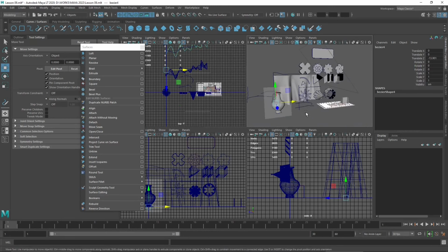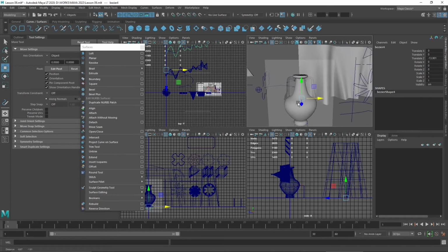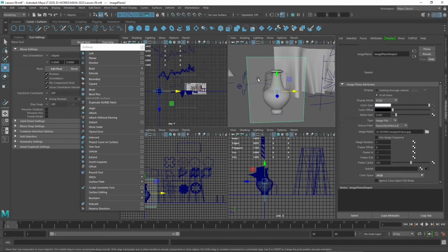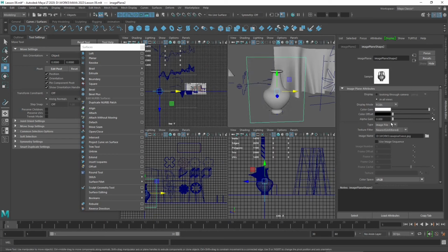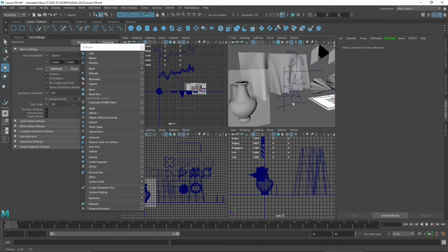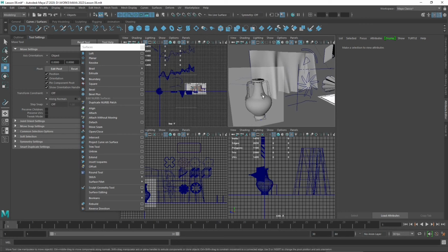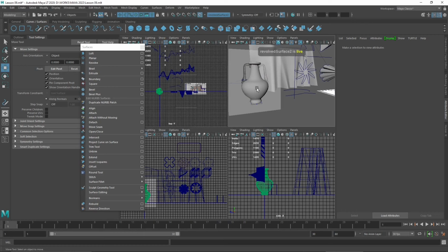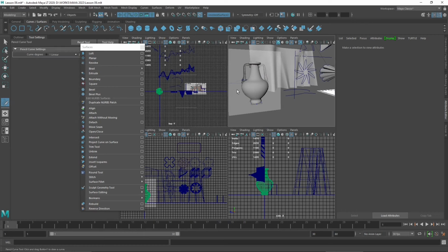For example, here we created a tent or a curtain using curves, and if we modify the initial curve, we can modify the result object. Same as the base here that we modeled before using a curve and tracing the image, and then we use the revolve tool. So we also saw how we can use images and references, which could be directly from Adobe Illustrator, from AutoCAD, or from other websites like Images.